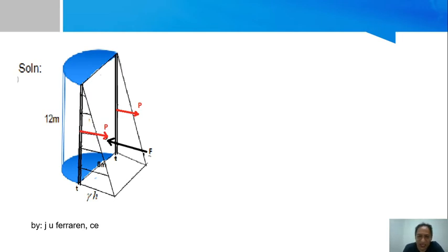Okay. So, my hydrostatic force, no? Which is this one. Actually, the pressure here is not actually uniformly distributed. As you notice, no, that is increasing linearly as there is a variation of the height h. No, it increases from 0 to a value. So in this is h, so that is unit weight times h. So that is the pressure diagram.